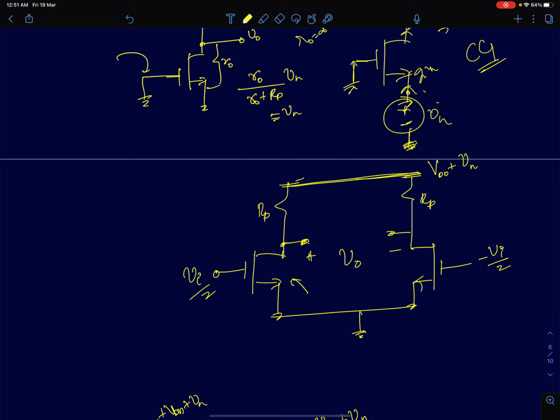So you have two identically biased MOS devices and two similar resistance values. And I'm going to bias both these amplifiers using the same supply voltage, VDD, the noisy supply voltage. VDD is the supply voltage and it has some supply noise riding on top of it, a 50 or 100 Hz or 120 Hz noise.